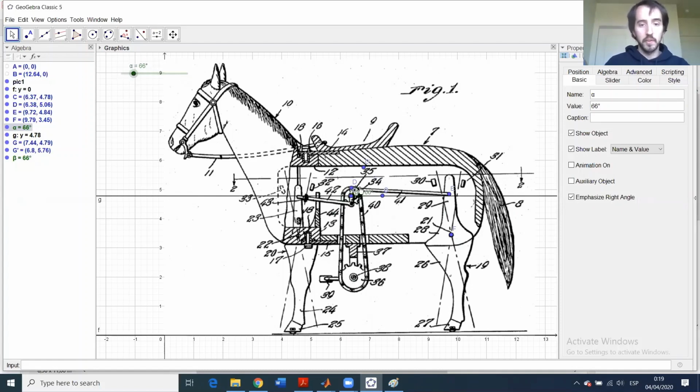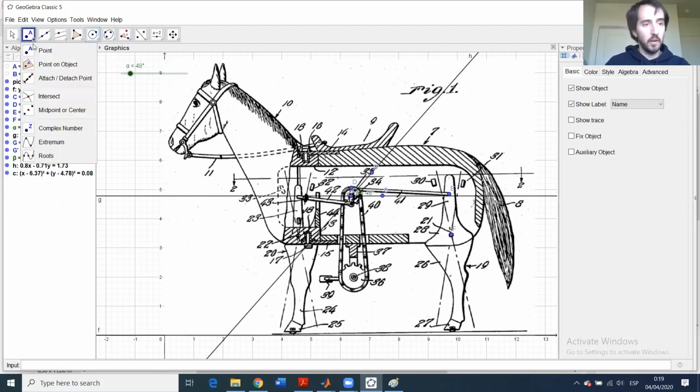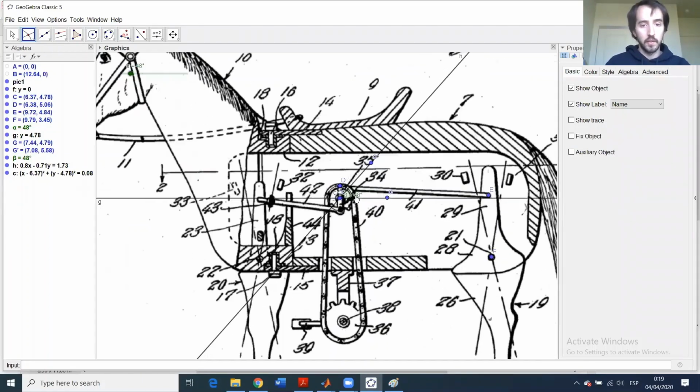So we want this point D here to be moving. So we have to create, with G, another point at a lower radius that intersects the line formed by these 2 points and the circle created by these 2 points, right? So we have created the line, the circle, and we will create a point that will be the intersection of these 2.